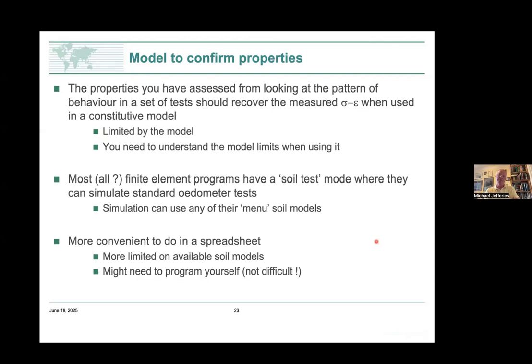But even though it sounds terribly complicated, you can program any of these models yourself, because what we use is Euler integration. Any plasticity model, in effect, takes your current stress state and tells you what the tangent stiffness is.